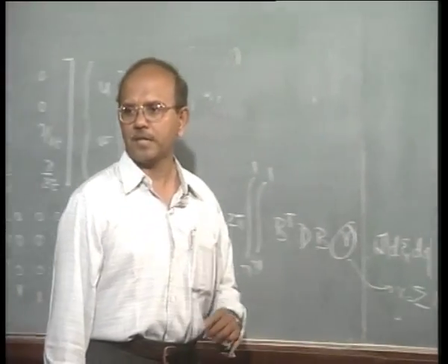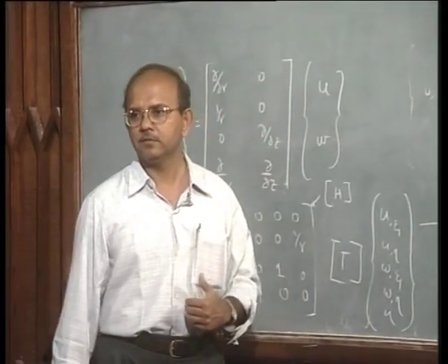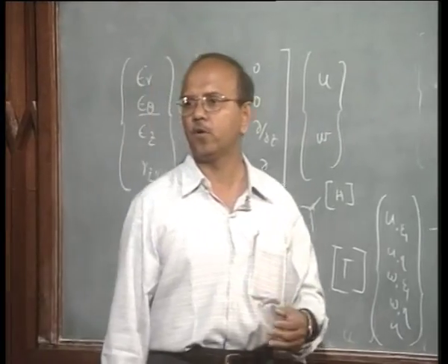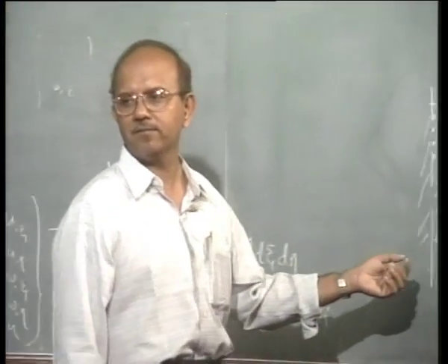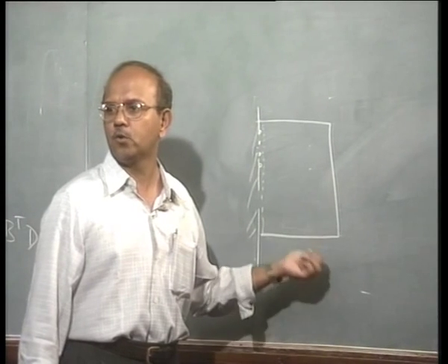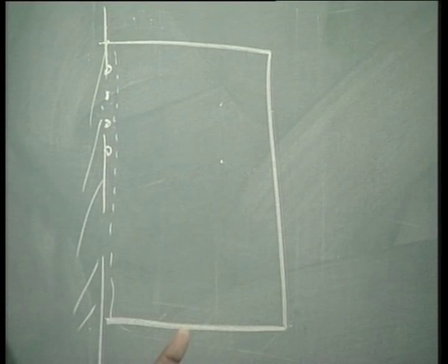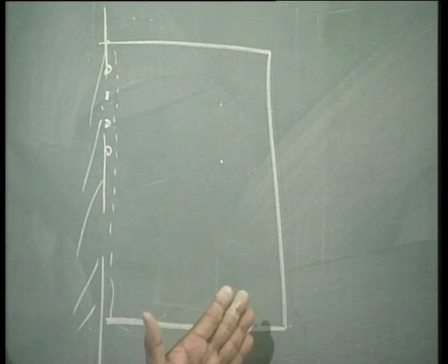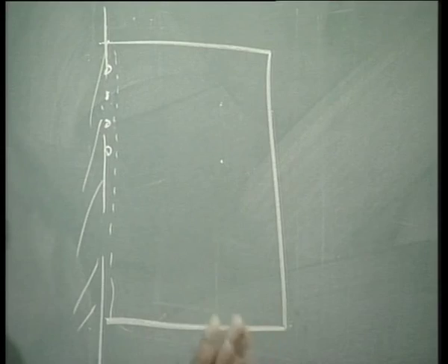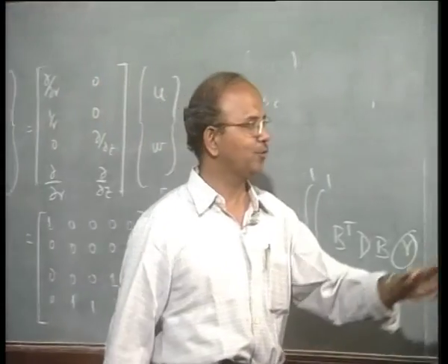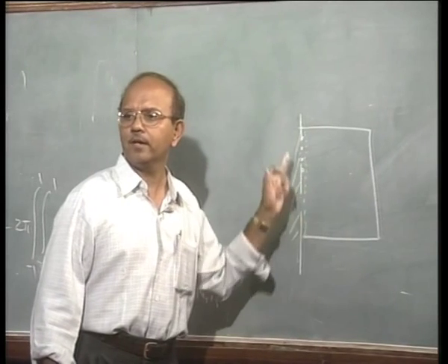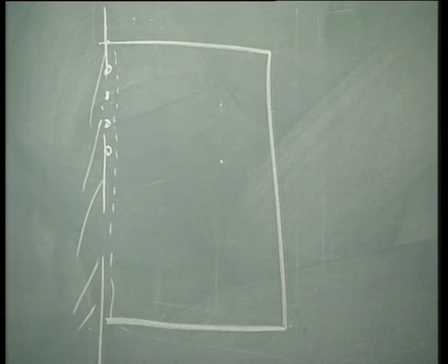Now, if this happens, especially if you are working in a company, you will be hard pressed to explain to your boss why a hole has been created. Okay, he is immediately going to ask, oh, the material has failed at the center, a hole is created. Then he is going to ask why there should be a hole at the center that is created like this and so on, because this has happened to me before, and then it's very difficult to explain to people. So just to have a nice result, one of the reasons you fix these nodes, okay, at r is equal to 0.